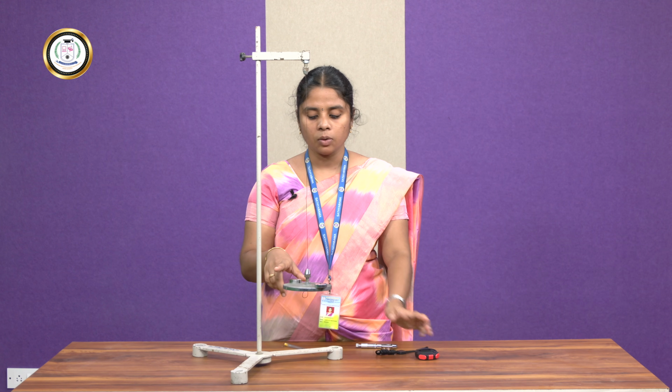So this is our trial one. Stop the circular disc after the 10 oscillations, repeat the same experiment and note down the time taken to complete the rest of the 10 oscillations, which will be your trial 2. So note down the time period for trial 1 and trial 2 in all 3 positions. Make sure you are maintaining a uniform length of the suspension wire throughout all 3 positions. That is how you need to measure a torsional oscillation in 3 different positions.